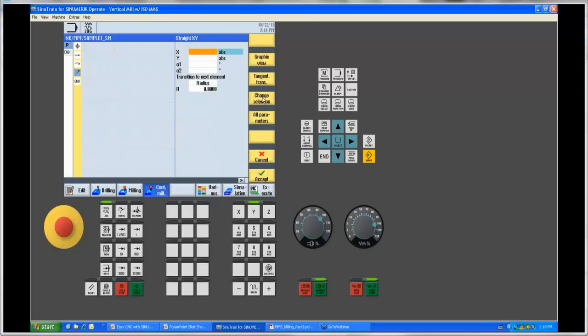Now in this shape, I'm coming down with a 2-axis move. I'm moving over to 4 inches. I'm coming down to 1.802. We accept it. Now I move down. If I had been dimensioning the angle, I could have certainly inputted the angle here. Now we're moving down in the Y, straight down.